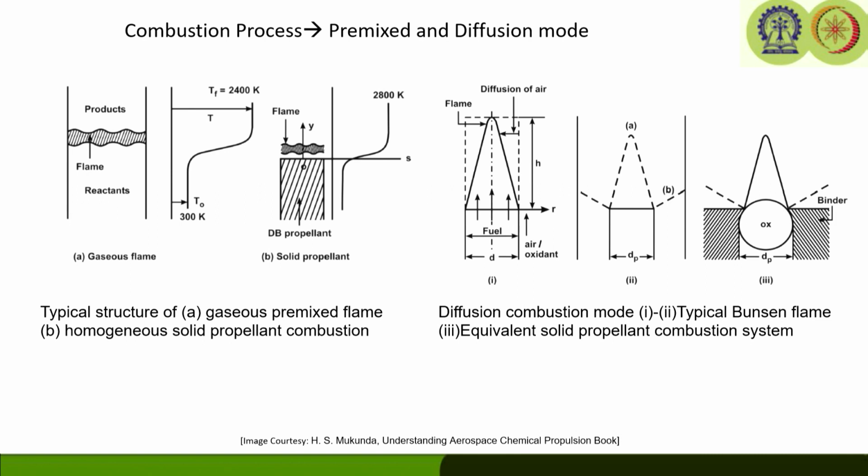Now, the combustion of solid propellants involves many complex reactions which take place in solid, liquid and gas phases of a heterogeneous mixture. There are several processes involved. As I mentioned earlier, the processes may include change of phases, like solid to liquid, liquid to gas. There may be high speed flows, chemical reactions, endothermic and exothermic, and both heat and mass transfer involved in the processes. So, modeling these types of processes in a very simplified manner is a very difficult task.